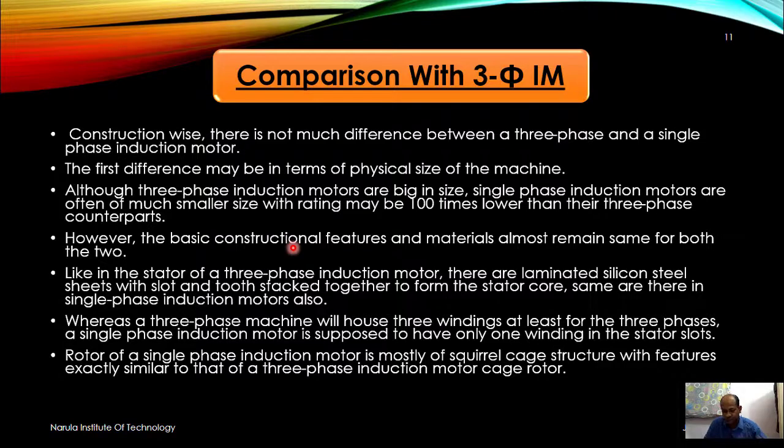So what we have seen is that the three-phase induction motor is a self-starting motor, but when we come to the single phase induction motor, due to the presence of a single phase winding, it fails to produce a rotating magnetic field.